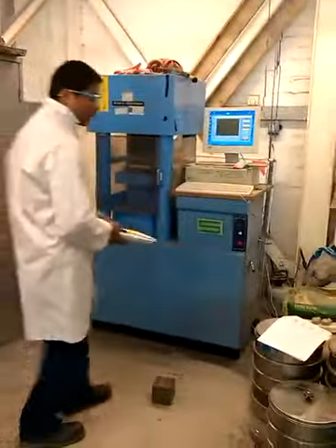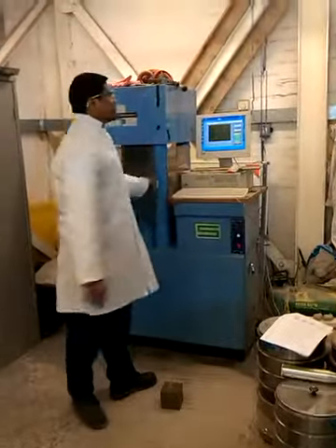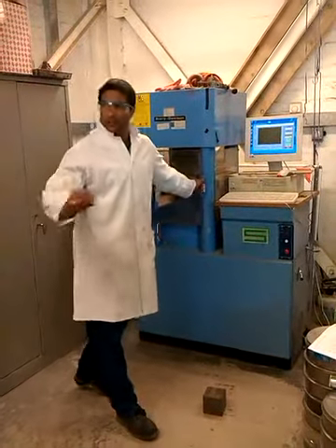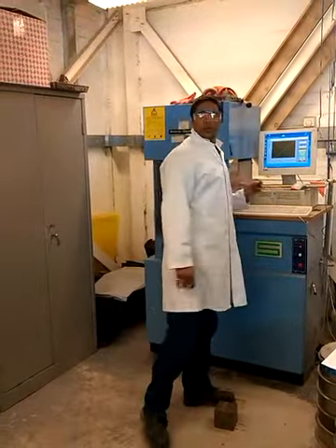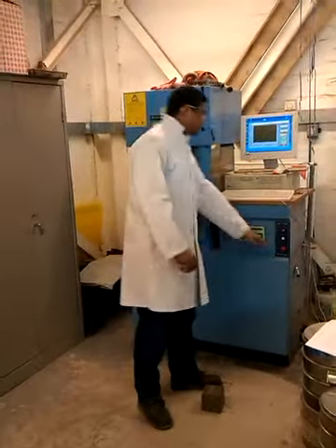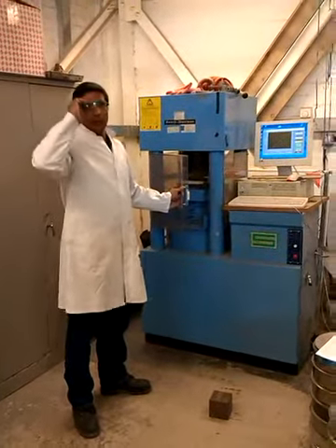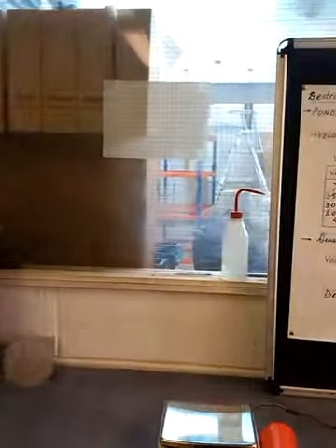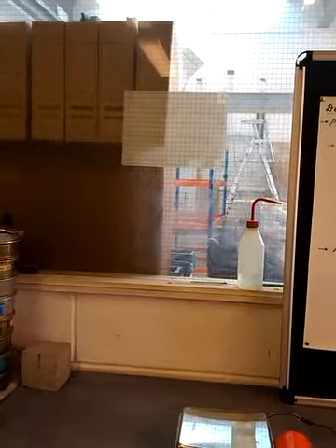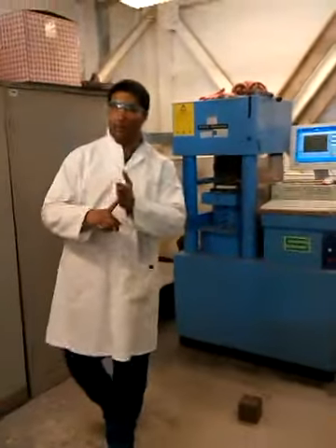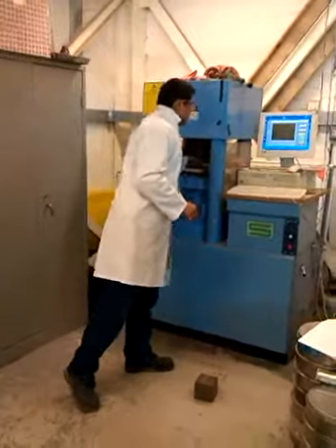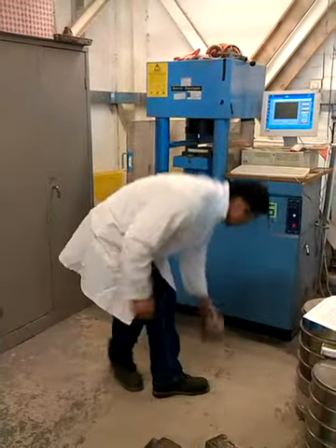Now the maximum load over here is 341.29 kilonewton. Write it down. 341.29 kilonewton. Did you get it? That is in kilonewton. So that peak load for your compressive strength must be converted to Newton. If you divide that by the contact area, 100 millimeter by 100 millimeter, you will get that strength. And you will compare it with our target strength, which is C30, 30 Newton per millimeter square. Okay? Right. That's the first one. Again, second one.